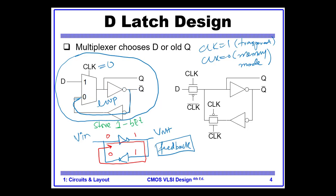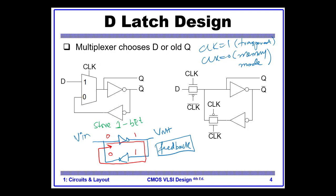What is the difference between this circuit and the circuit which consisted of 2 NOT gates? The difference is that it has this clock signal, it has control. So it has the control signal. The control means that you can choose when to change the latch from memory mode to transparent mode. So it was the circuit number 1.